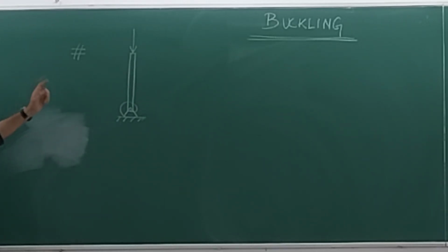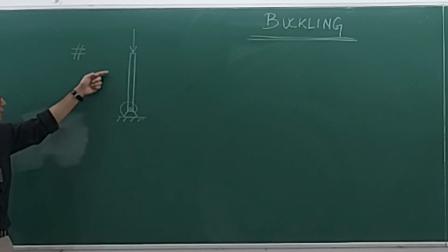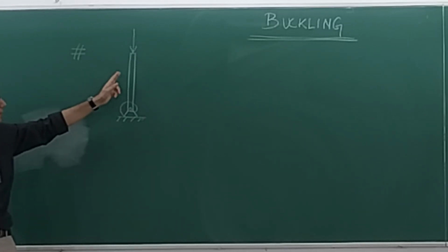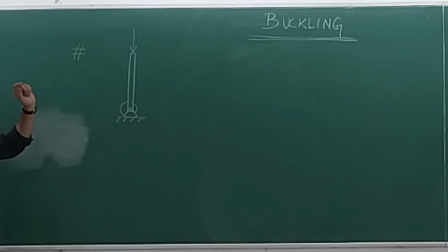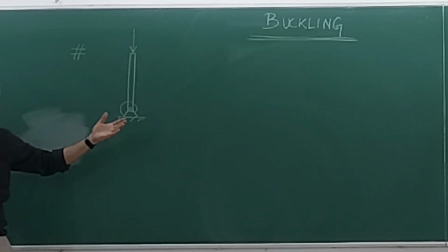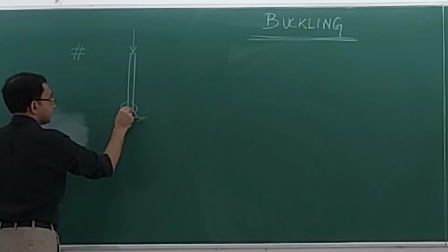But suppose I tell you that what I will do is, through a very, very small force, I will just poke it and I will disturb it from this position. Now, in that disturbed position, let us investigate what happens. And this will be the hallmark of all buckling studies. We'll have to disturb it and then we'll investigate it. Even when we go to mechanically deformable solids, which is what we have been doing all the while, things like beams, there also you'll see that we are going to deform it and then we'll investigate it. So step by step we'll do it.